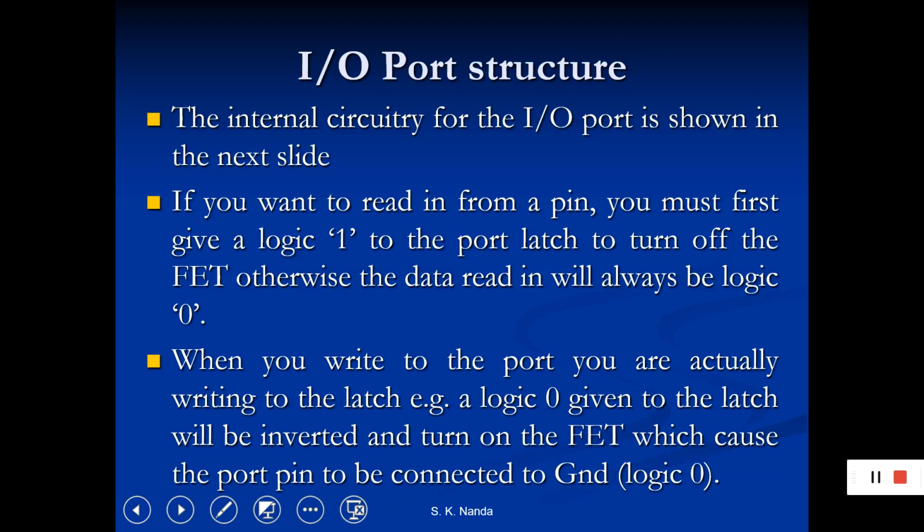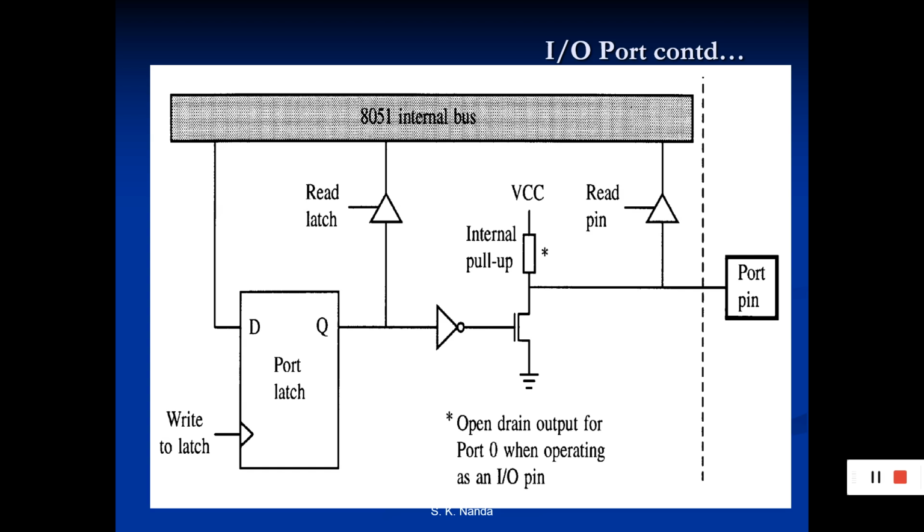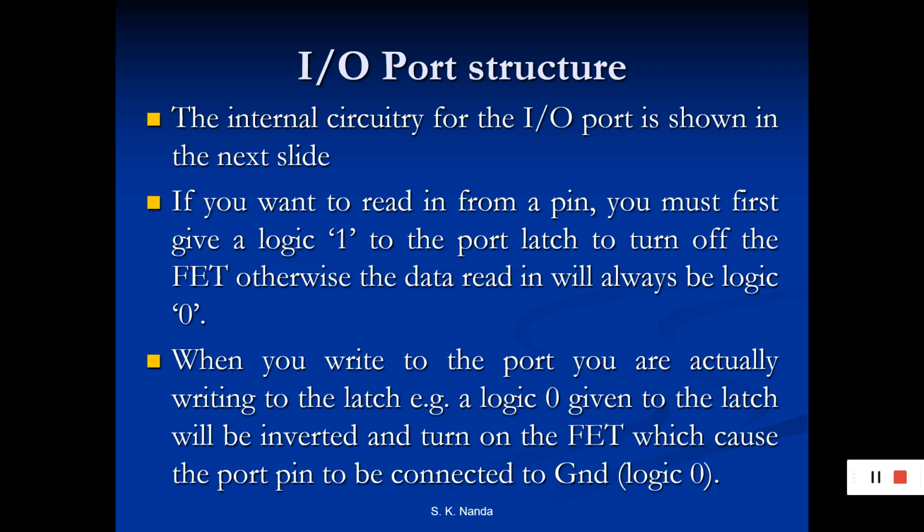Now, next is I/O port structure. 8051 microcontrollers have 4 I/O ports, each of 8-bit, which can be configured as input or output. You can see the internal circuitry. This is the internal circuitry. We'll come back to this. Hence, total 32 input-output pins allow the microcontroller to be connected with peripheral devices. The pin can be configured as 1 for input and 0 for output as per the logic state.